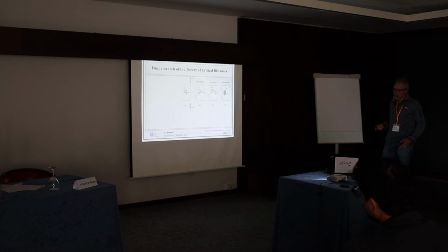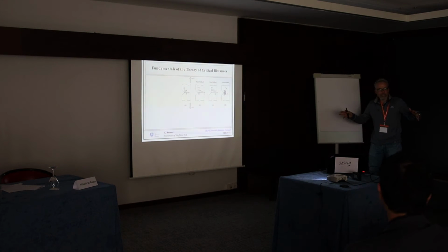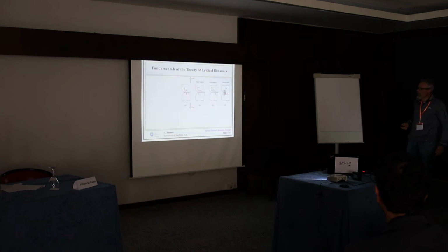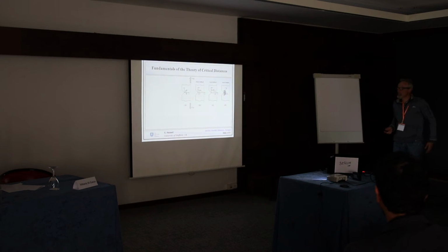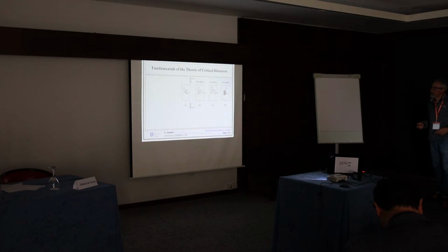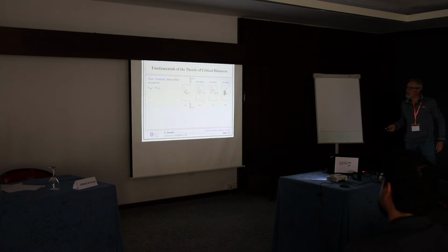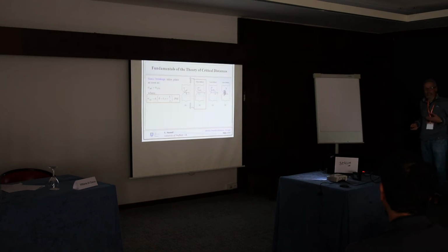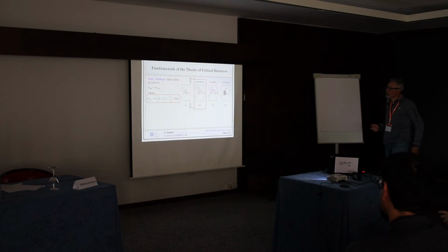The theory of critical distance is nothing but a body of knowledge that has been developed over probably longer than a century actually, and giving to this theory many different names. So we have two fundamental ingredients. The first ingredient is an effective stress, and the second ingredient is a material strength. The effective stress can be defined in many different ways. For instance, according to the point method, we get the effective stress at a certain distance from the notch tip, where this distance is L divided by 2. Remember L as defined in the previous graph.